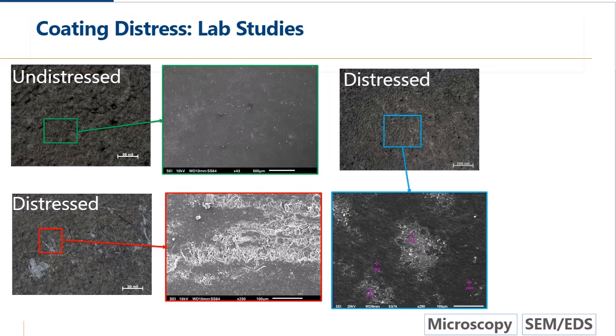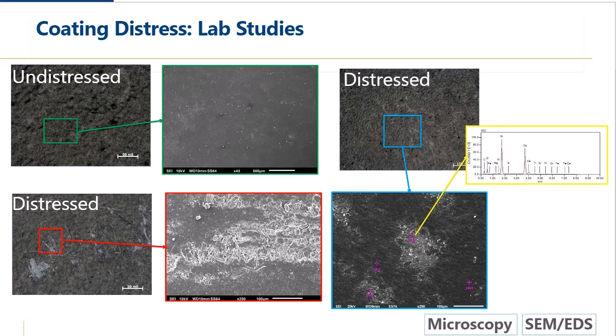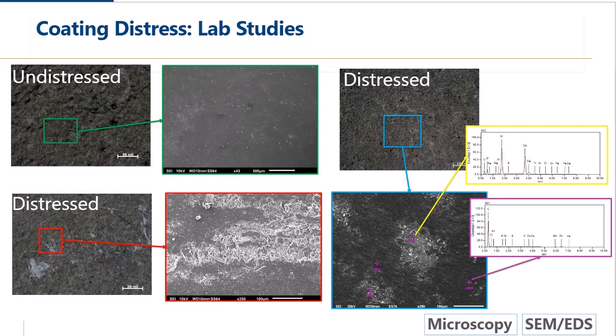But we will look at that area in the SEM. We see blotches of a material that looks a little different compared to the surrounding darker colored material. And when we look at them, we use the EDS for elemental analysis. If we look at that circular patch in the center, the EDS tells us we've got a lot of silicon and calcium and oxygen and other elements that are very consistent with a fiber cement panel. So this is what we expect to see. And then we look at the more uniform area and we see a lot of carbon. We don't see a lot of other stuff.